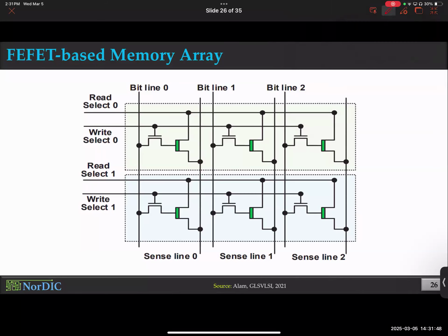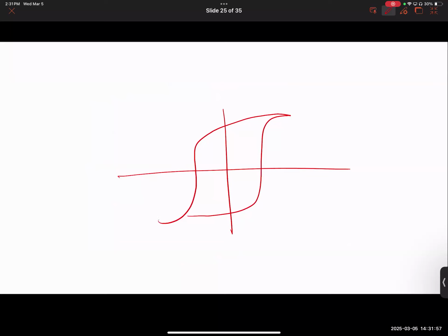It's a great question. Typically the write asymmetry is very, very minimal. They can, especially because I haven't showed you those results. We have been looking at ideal ferroelectric material mostly, so uniform plus EC, minus EC, coercive voltage or coercive field. But there are situations where there could be skewness in the ferroelectric. It could be plus EC1, minus EC2, like there could be a difference there. If that's the case, then yes, for sure.